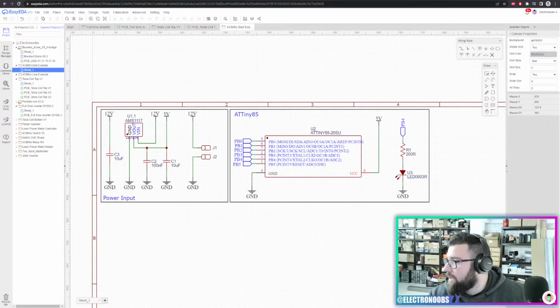Using a shunt at the high side of the bridge is not a better idea for short circuit protection. Why? The shunt is made to measure the current value. It's not for protection. If you want protection, just add a fuse. And you can add a fuse at the input, the positive input of your circuit.